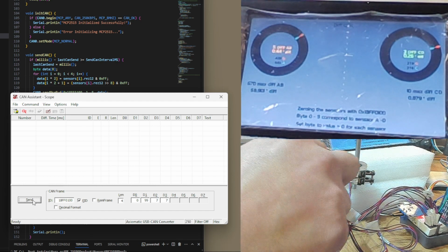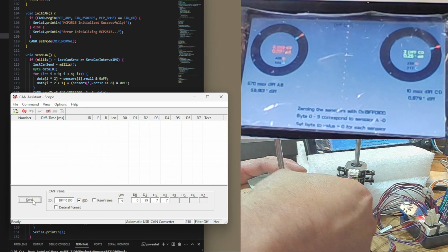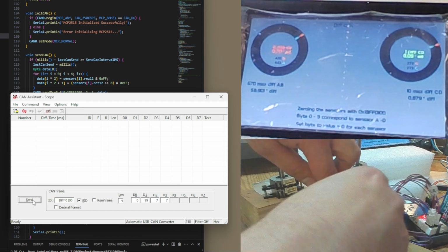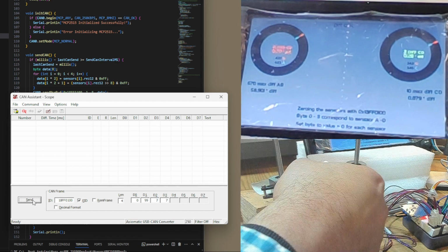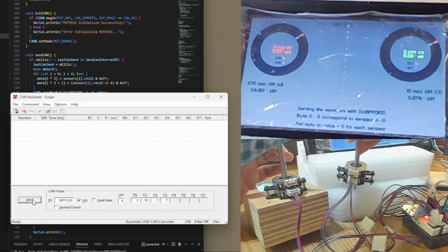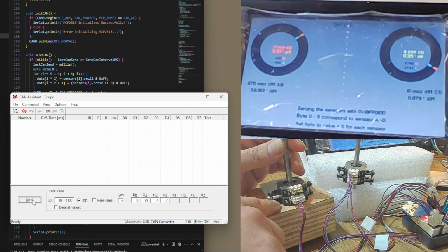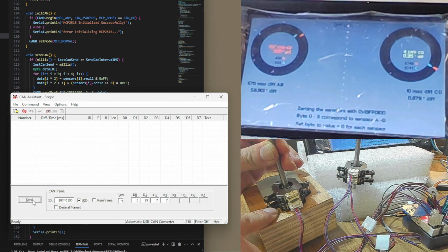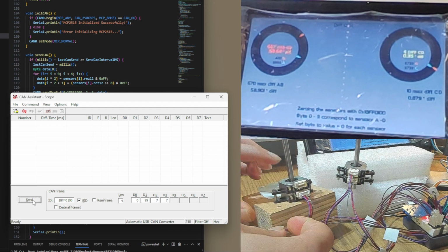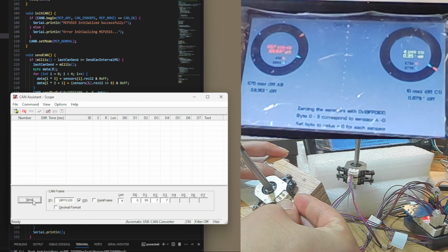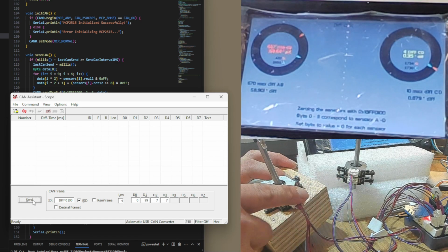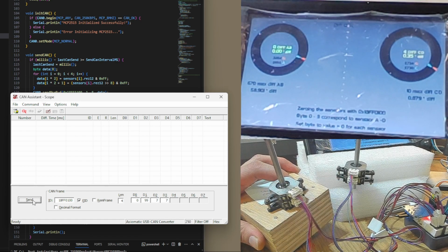It doesn't matter where these cables go, they're completely interchangeable since all of the sensors are on the RS485 bus, and we'll just wait for an ID to respond. So as we see here, this one will still work. This one will only move one since we only have one connected. And look at what happens when we connect the second one. Since they are both physically connected to the same axle, as soon as it powers up, it will broadcast its value. So boom.